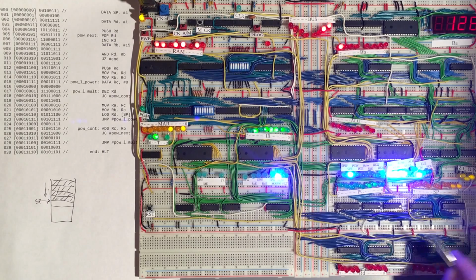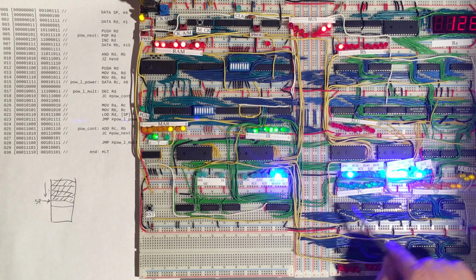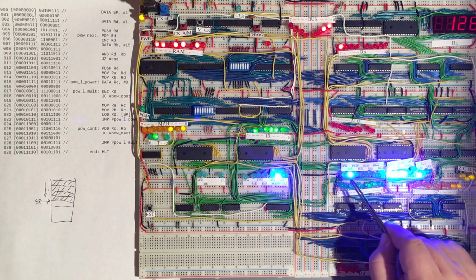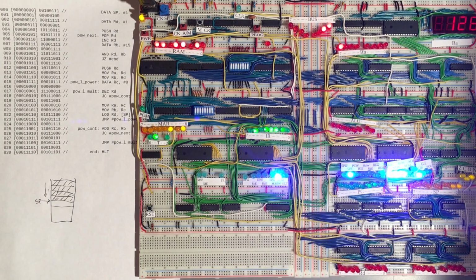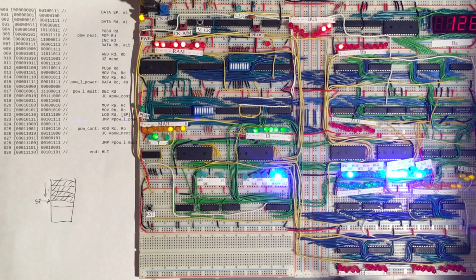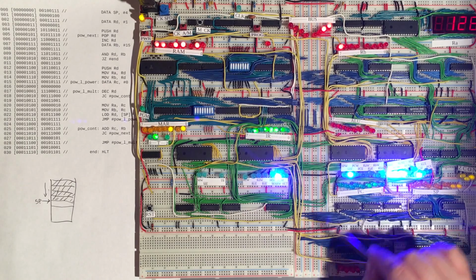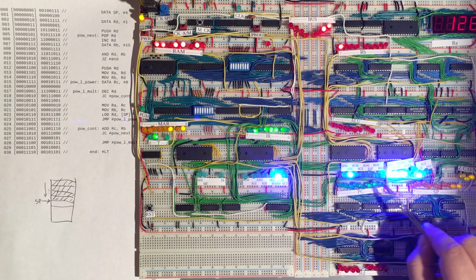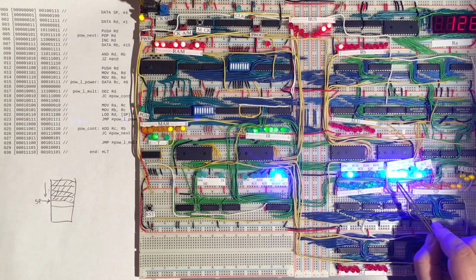And so this 3 at the moment is being enabled on the bus, and is in fact going to be written into the memory address register. And so far that looks like the first microcode cycle of a load instruction. But in addition, we're activating the ALU here. And so this 3 from the stack pointer, which is out on the bus, is going not only into the memory address register, but in fact is also being processed by our ALU.